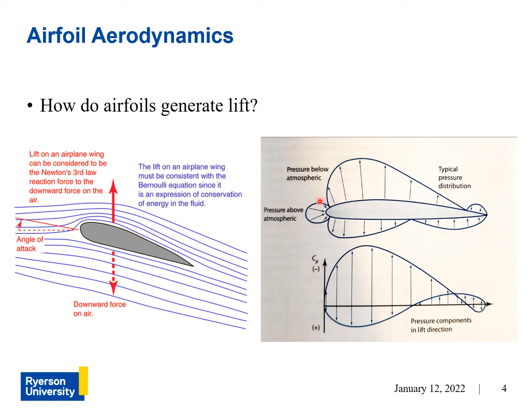Now, there are a lot of misconceptions when it comes to the generation of lift due to an airfoil, and one of them is that the length of the upper surface of an airfoil here actually has no effect on the speed at which the air travels. Okay? That's an incorrect assumption associated with the longer path or equal transit time theory.